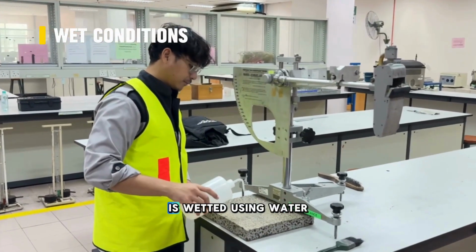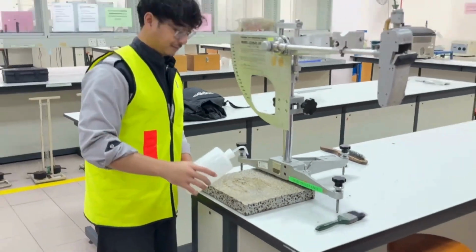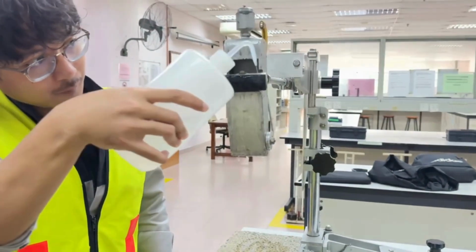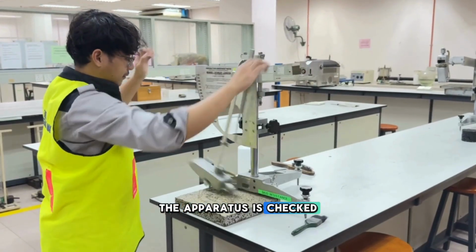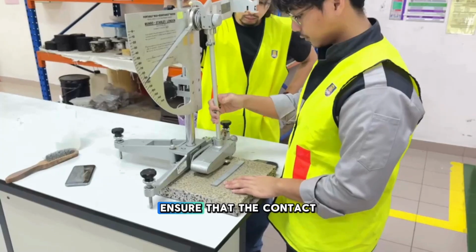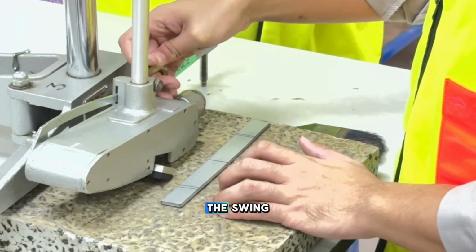After that, the surface is wetted using water according to the surface condition. The rubber slider is also wetted using water. The apparatus is checked again before conducting the test on the surface. Ensure that the contact between the rubber slider and the surface both before and after the swing is within the acceptable range.